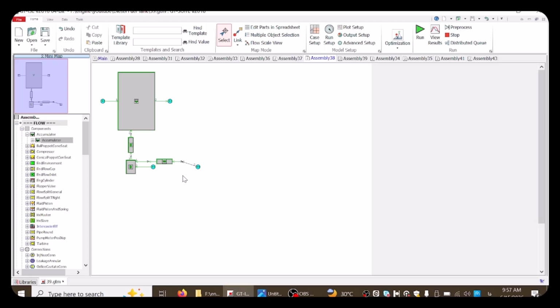It will have a filling pipe, normally from deck. It also has a vent. This is very important as the tank is not a pressure vessel. As the tank is emptied or filled, air has to be allowed in and out. So, ideal tanks also have a drain on the bottom to drain water and sediment after it has settled.